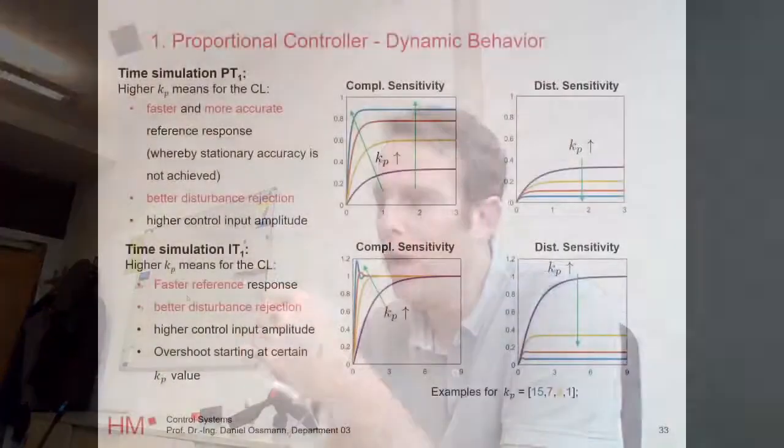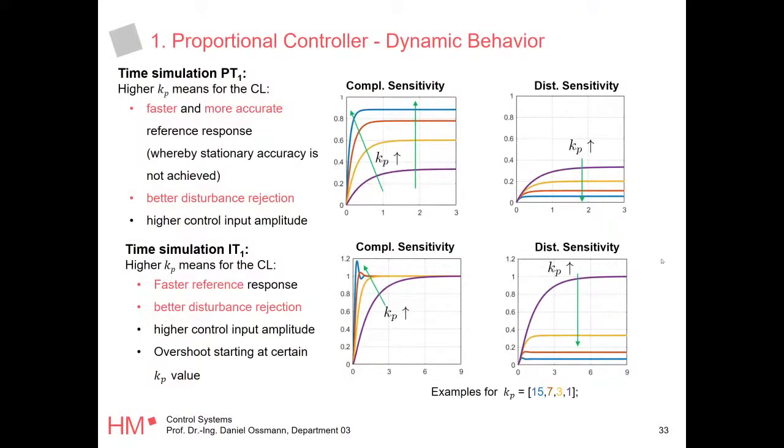So in a closed loop, we don't have an integrating system anymore. We have a stabilized proportional PT2 system, right? However, the disturbance rejection is not perfect. Again, there's something remaining. If you increase the gain, it gets better. However, here, well, the oscillation is not very big, but it starts oscillating. Okay? So let's sum up what we have for the proportional controller.